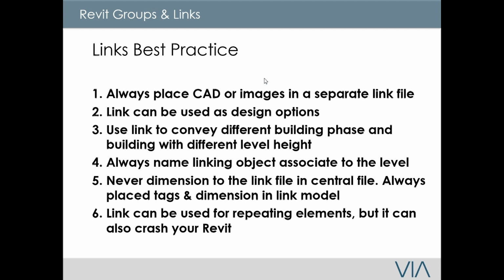And also, if you put images into Revit, it will add size to your file. So if someone puts in 20 megabytes of, let's say, an aerial photograph, what tends to happen is that it will add 20 megabytes to the Revit file size. So imagine you have 20 of those, and that file size could balloon up to almost quadruple the size. So if you have to do that, put it in a separate file.